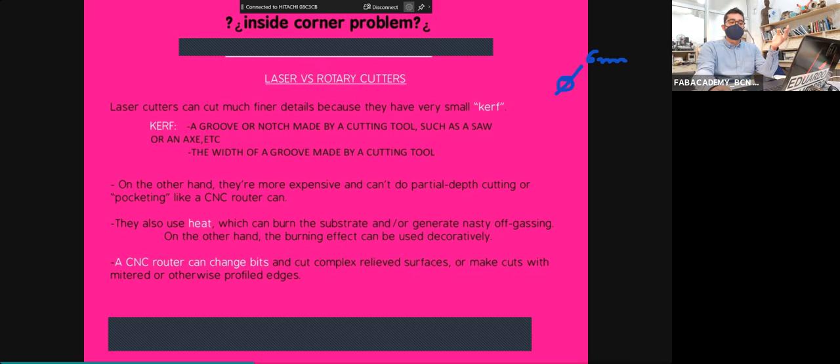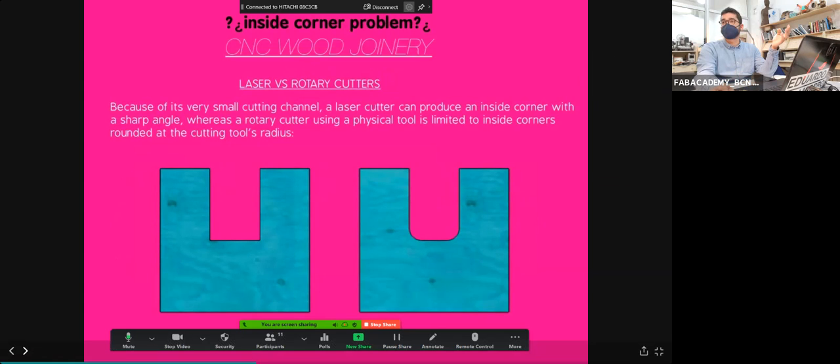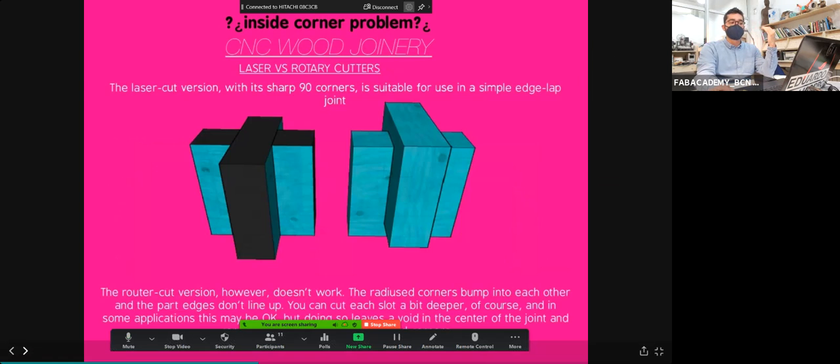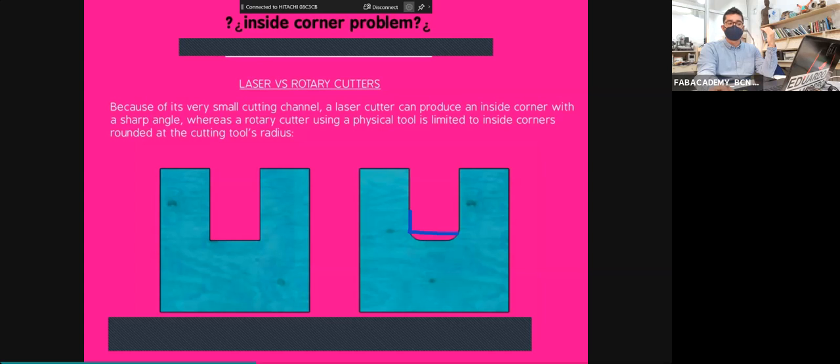We have a problem that when you're cutting in a line and you do an inside corner, this is a circle because we are cutting with a circular tool. If you want to have this design, this is what finally happens. The mill produces this. To avoid this in joineries, we need to produce what are called dog bones, T-bones, or I always like to call them Mickey Mouses. If you try to match the parts to each other, they don't fit. Why? Because this part cannot fit inside, it gets stuck here because the dimension changes. This joinery cannot sit completely onto this area.